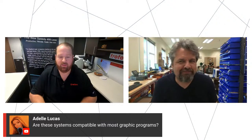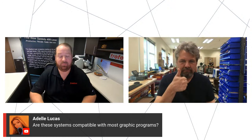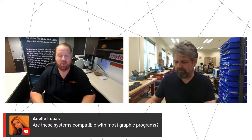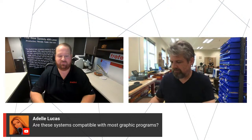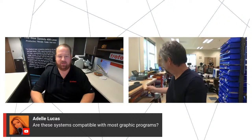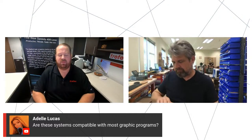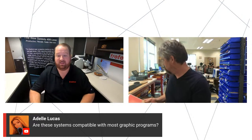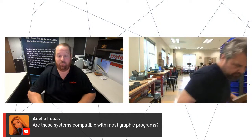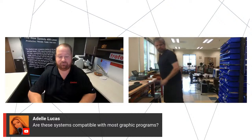Are the laser systems compatible with most graphic software? I can answer this. Yes, definitely. The graphic software does need to be vector-based in order to work. So any vector-based graphic software that can produce a cut line or a vector line, most commonly Adobe Illustrator, CorelDraw, your CAD-based software. Inkscape is a free one that's out there, and there are so many other free ones that can work. If you can draw a line and it's vector-based, we can process it.